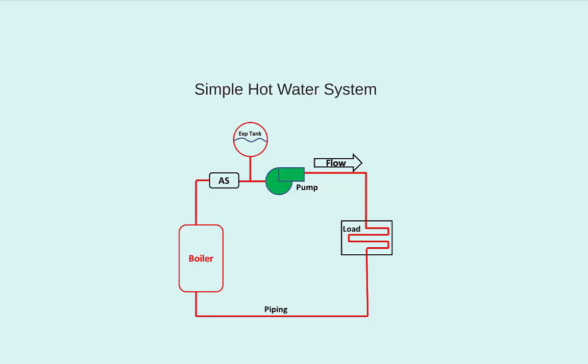We ensure that appropriate amount of pressure is maintained on the suction side by having the expansion tank located where it is, right before the pump. It could be put elsewhere, but the engineer better know what he or she is doing. So in essence, the expansion tank is kind of a control device. It ensures minimum required pressures are realized in the system to ensure the system operates as designed. Additionally, there is typically a pressure relief valve located in the piping leading to the expansion tank, which will bleed off pressure if it begins to get too high.